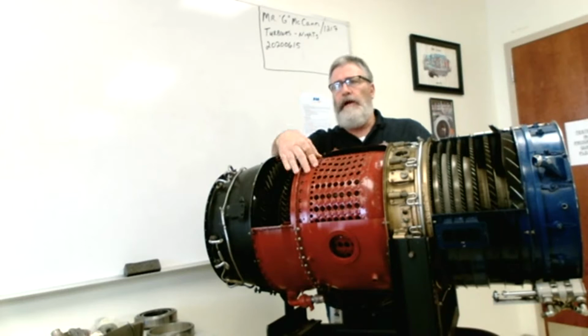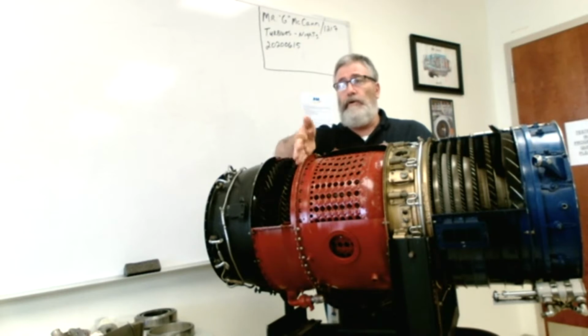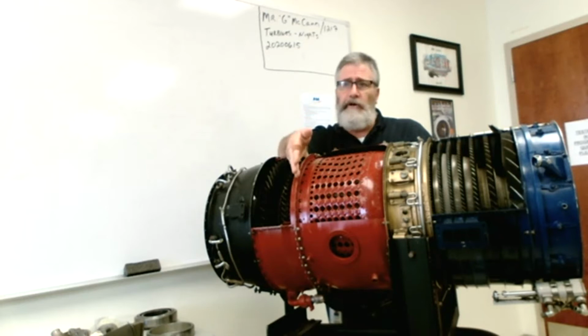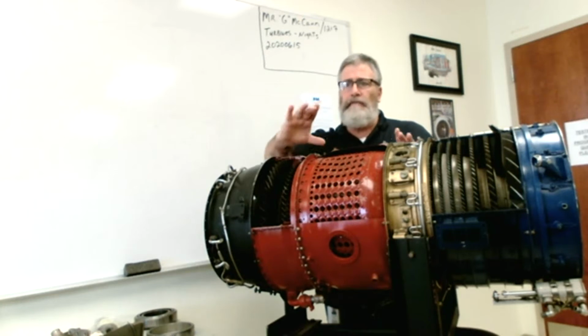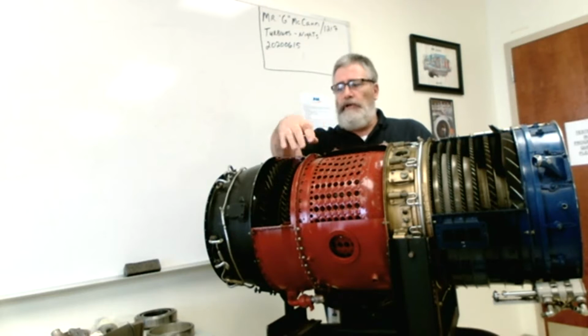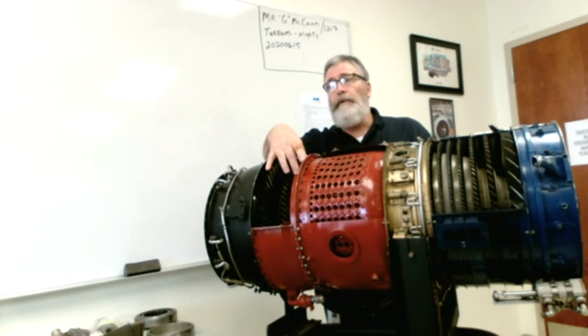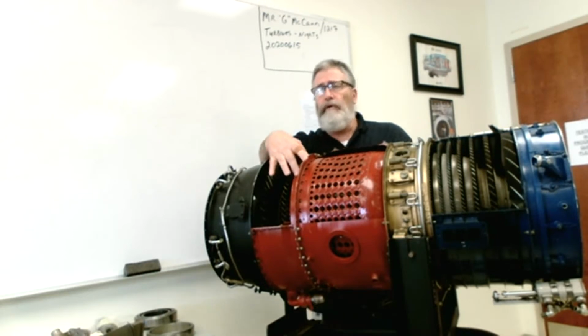So we've left the combustion area and we're coming into the turbine area, right? The first thing that this fire sees is referred to as a turbine nozzle. Sometimes the FAA refers to it as a stator because the blades are stationary, but it is actually a nozzle because it does have a specific flow area. The turbine nozzle is actually a convergent design because now we do want to increase speed and reduce pressure.